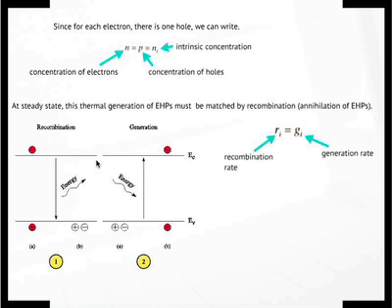Okay, the semiconductor is at a steady temperature with its surroundings. That's basically what that means. It's not gaining heat or losing heat. Okay? In that situation, these rates, of course, also depend upon temperature. As I said before, the carrier concentrations, of course, depend on temperature. So at a higher temperature, if you heat up your surroundings or heat up the silicon crystal, it will reach a new equilibrium.